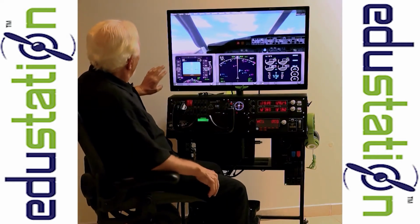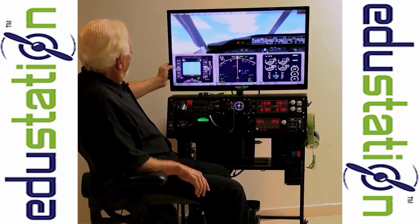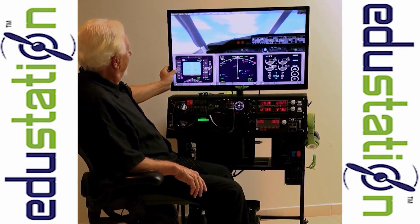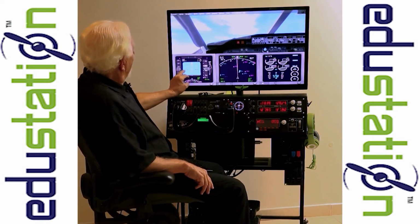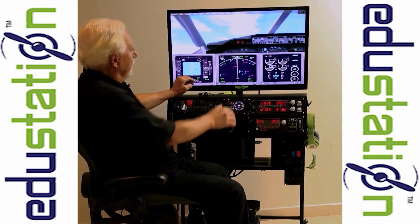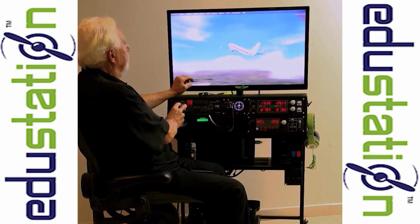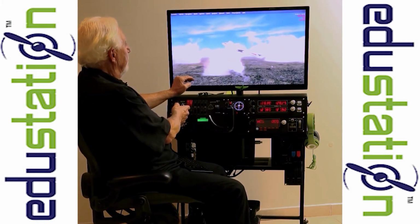And so now, this is called a glass cockpit. The tape on the left is our airspeed. The tape on the right is our altimeter, so we're at 5,600 feet and climbing. The center is our artificial horizon, and in this case we're at a 20-degree pitch up, which is a little too steep for me, so we'll push it down a little.